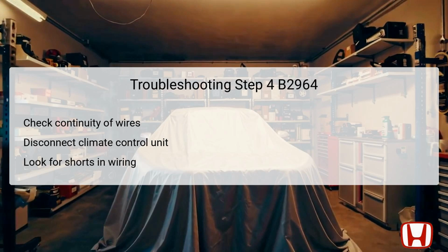After disconnecting, check for continuity between test points on the wiring. The specific test points involve number 299 on connector A and the body ground. By performing this check, you ascertain whether there is a short to ground somewhere in the bus data wire. If continuity is observed, this suggests that the wire is shorted to ground, requiring immediate repair to prevent further damage.